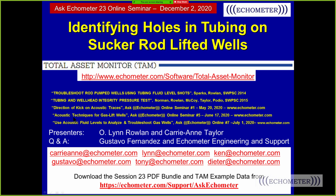And then we talked about shooting fluid levels on gas lift wells. Carrie Ann did that presentation, and it was on using not only fluid level shots, but a technique called dual shot, where you shoot down the tubing with a gas gun, and you have another gas gun attached to the casing, and that gas gun is listening.